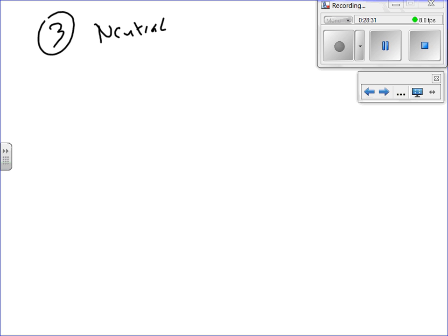Neutral. Okay, so what was the number that we came up with? The amps. 903 amps. I have to parallel by 4 because I did the phases by 4. So that will give me, DJ, 226 amps, right? Everybody's cool with that?